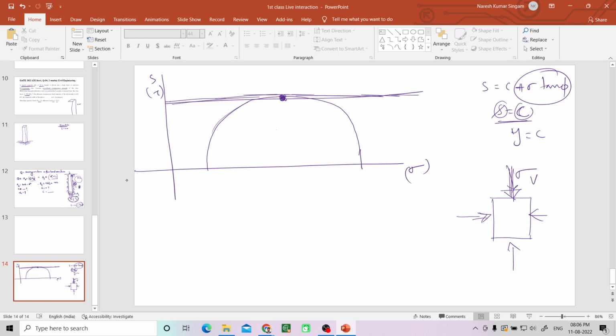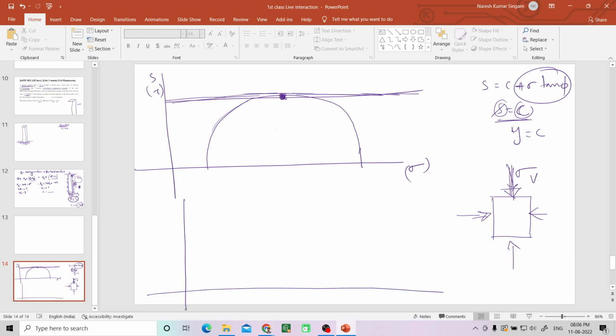Now to draw that new Mohr circle, this is 0, sigma 3 or sigma H is 0, right? And sigma 1 you can take as sigma D, the deviatoric stress at the failure. At the failure it is still 0 for confinement, but it is having some value. Now there is no shear stress on any plane because it is completely unconfined. So here 0 comma 0 is this plane. And what about this plane? It is some sigma D, or let us say sigma 1, which is sigma 1 comma 0, tau is 0. Now these are the 2 points on 2 perpendicular planes. I explained, to draw a Mohr circle you need 2 points on 2 perpendicular planes. Now one is 0 comma 0, another one is some value, sigma 1 comma 0. Now you draw a Mohr circle, right?